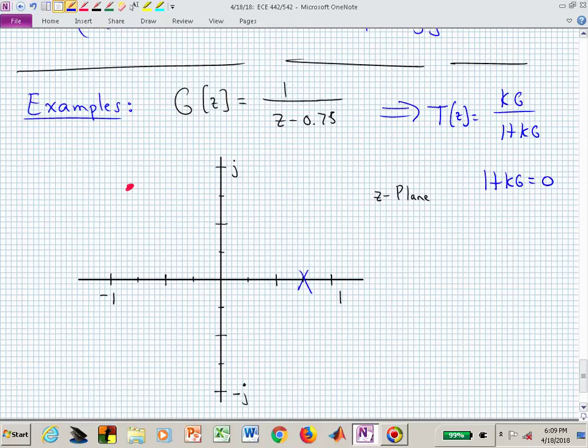And you would go up here and you would say, let me find all of the angles associated with these poles and zeros. You don't have very many poles and zeros. That's supposed to be a straight line, and you would measure the angle from that pole to that red dot. And you would say, okay, I have all my zero angles added up. I don't have any of those, so that's nothing, minus all of my pole angles. And there's my pole angle, theta sub p.